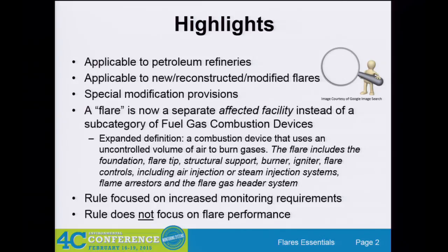One of the other things that they did, and this was how they're going to get probably every refinery flare into JA at some point, is they expanded the definition of flares to not only be the flare stack. Now they're saying the flare is everything from the flare stack to the seal drum to the knockout drum to the entire header. That way, if you add a single connection, you've increased the flow potential to that flare, which has increased the potential emissions from that flare, and therefore you have modified that flare.